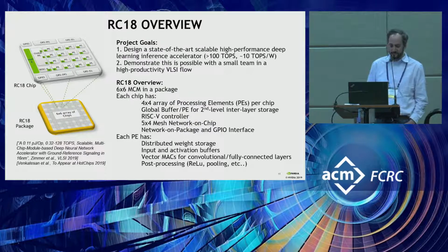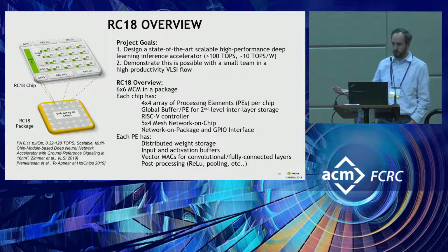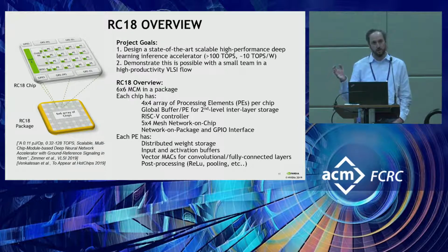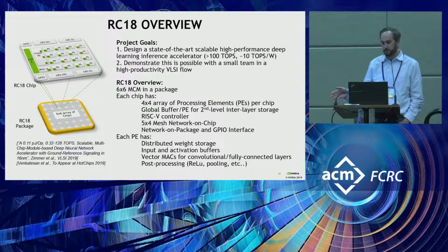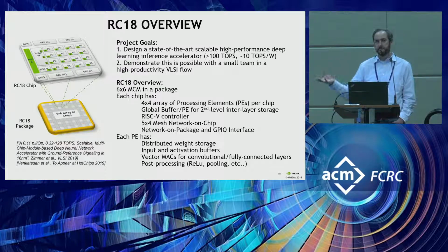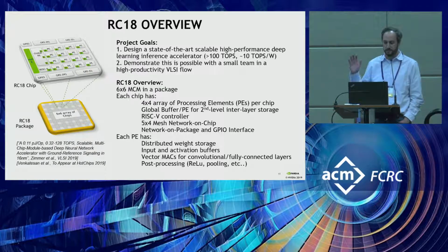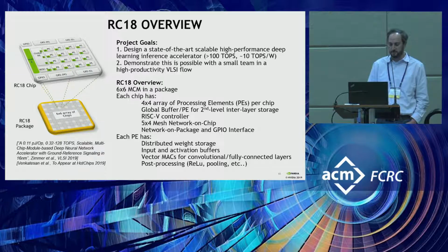We just published this 2 weeks ago at VLSI, and it's also going to appear at Hot Chips. The goal of the project, as I mentioned, was to achieve over 100 teraops of inference performance, 8-bit integer, and get about 10 teraops per watt, which is pretty much state of the art, and demonstrate it's possible with a very small team in a high productivity flow.